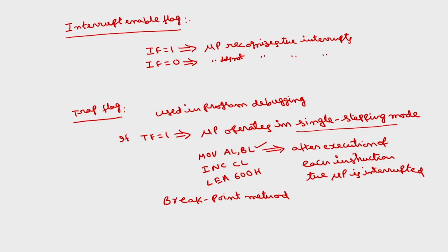This is the third operation we are discussing, the internal data operations. The first one is storing the 8-bit data, for which we need various registers. The second one is performing arithmetic and logical operations, for which we need an ALU. Then the third one is testing for conditions. For testing conditions, the microprocessor needs a hardware element called the flag register. I have discussed the different flags of the 8086. Then the fourth internal data operation is sequencing the execution of the instructions.